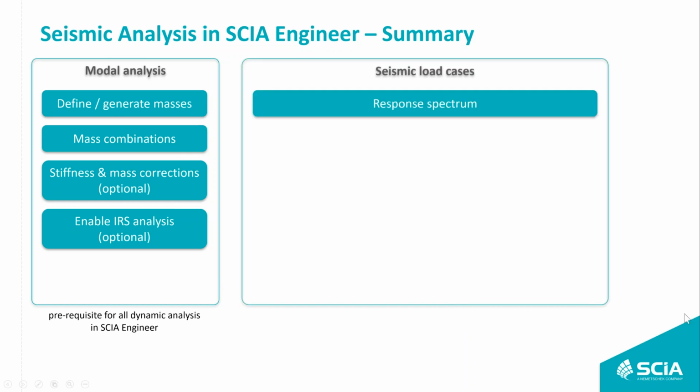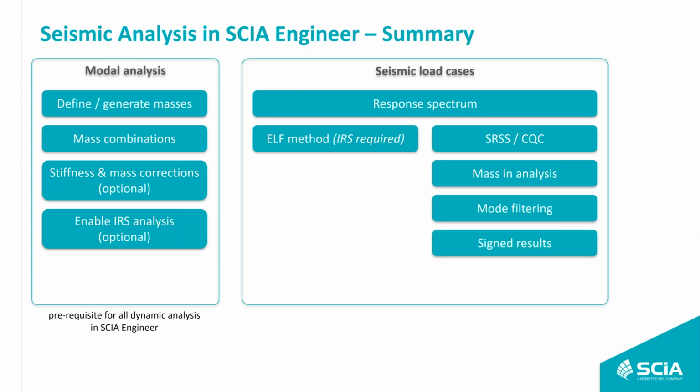And then the seismic load cases. In all cases, obviously, create a response spectrum. That's the basis. You can carry out an ELF calculation in this case. Note that the IRS calculation is required because the storey information is used to calculate the storey forces. That's the reason why. Or you go for a typical standard response spectrum analysis with modal superposition, defining the modal superposition